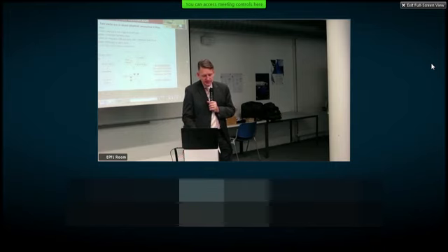So how do we describe it? Well, here's an OPM model of, I'll give you a couple examples from xerography. So we have a main motor here, number 1, and then 2 different clutches, number 2 and number 3. And the process linking them is engaging, right? The main motor engages through the clutch. We can hide the process, and then we just have this bidirectional interface between 1, 2, and 1 and 3.